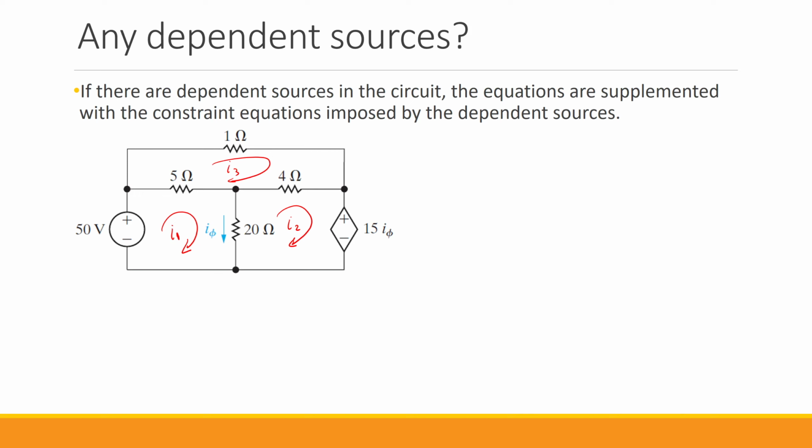So when you look at this circuit, you see that if we went with node voltage method, it was much easier, right? Because for the node voltage method, here we had this independent source that are connected to this essential node. If we consider this to be the reference node, that means that the voltage at this node is already there. So we only need to figure out the voltage in this node and this one, right? But for the purpose of this video, I want to use the mesh current method. So let's just write the KVL for each one of these individual meshes.